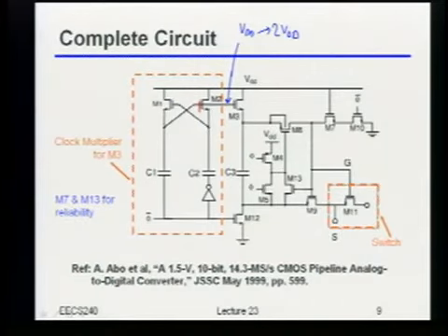So just in case you haven't seen it before, the way this thing works is something like the following. Assume for a second that this starts at VDD. Just believe me that somehow magically it got there initially. When this clock signal rises from 0 up to VDD, that'll capacitively couple and kick this voltage up, right? Roughly speaking, it should kick it up to about 2 VDD. Once I kick that voltage up to 2 VDD, notice this NMOS transistor should turn on, right? Once this thing is on, this right here is just VDD, so this point should also go to VDD. I'm just clamping it to VDD.